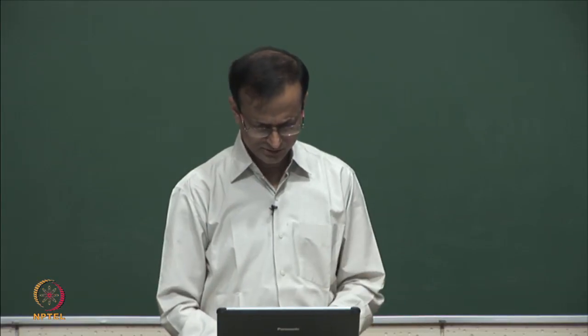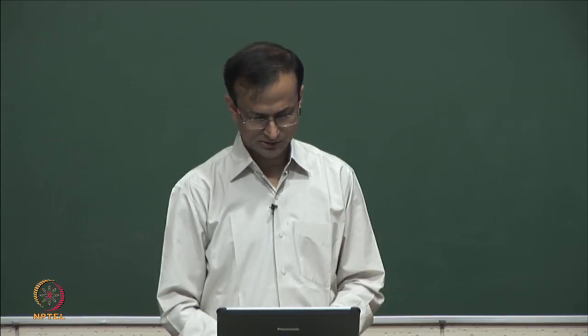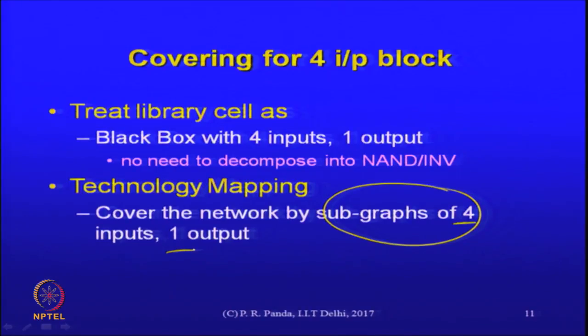So, this is all I wanted to indicate that would be a variation for technology mapping. There is the other issue that I have a fixed number of functions in each of the CLBs and so on. So, other complications are there, but the principle is just this. What changes from the standard logic optimization procedure? It is just this. In fact, it looks like it is a simpler problem for us.